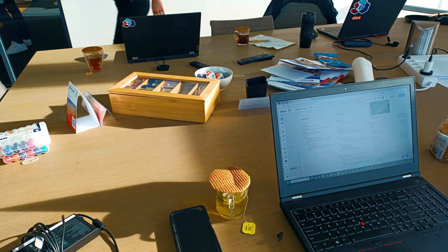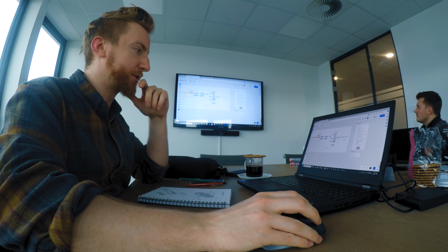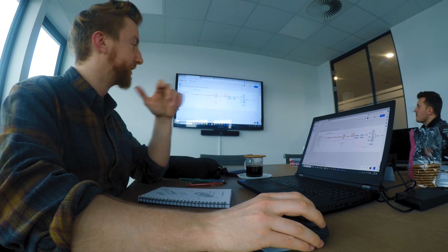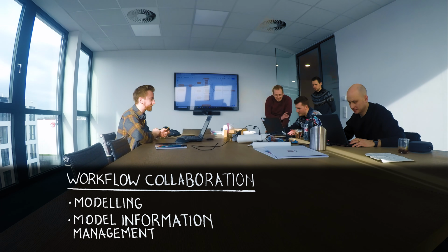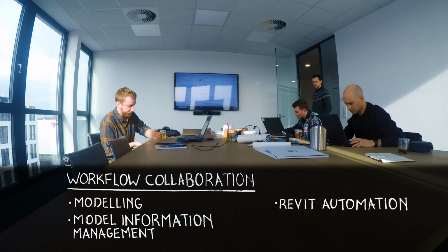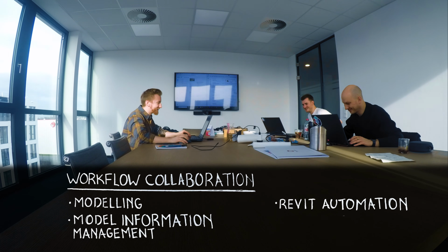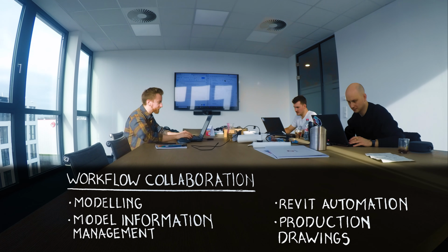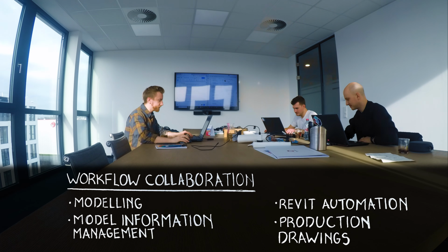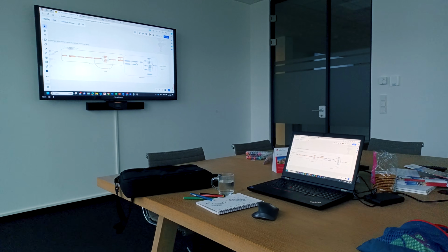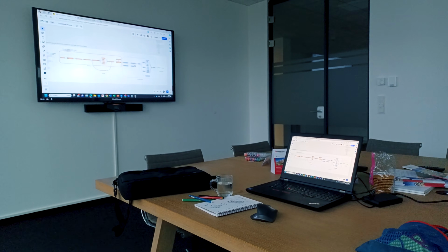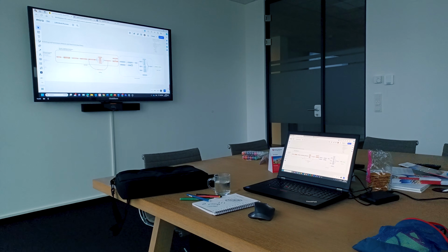After an hour of intense work, it's time for a cup of tea. We start by presenting our individual workflow proposals for the project. These cover how we model metal stud frames using the AgaCAD add-on for Revit, adapt 2D drawings for efficiency, and create production drawings for modular elements like concrete floors and steel beams. We decide on one proposal as the foundation, then go through it step by step, questioning, refining, and improving until we have a clear shared process everyone agrees on.